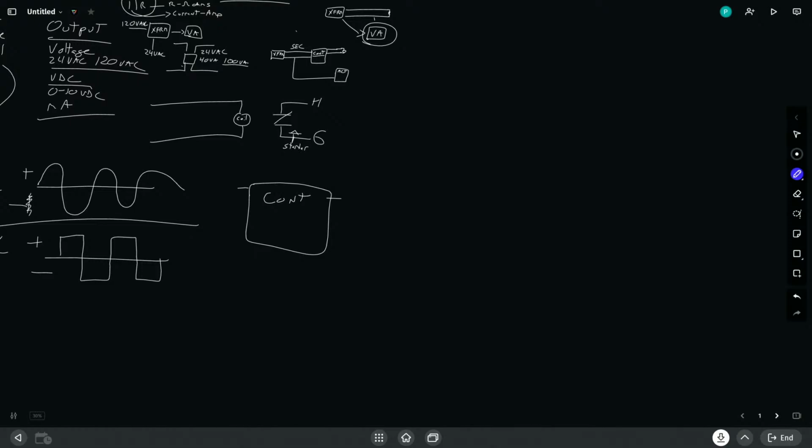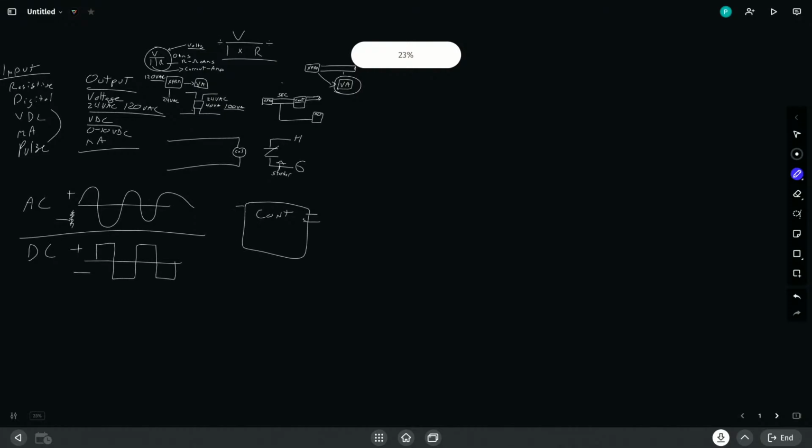This becomes specifically important when we are using externally sourced power and routing that through our controller output. So if we have a relay output inside our controller and that relay opens and shuts inside our controller, then we need to be cognizant of the amperage rating for that output so that we don't put too much amperage through that output. That can cause the controller to be damaged, sometimes permanently, and that can just be a very bad thing. So there you have it, some electrical concepts.